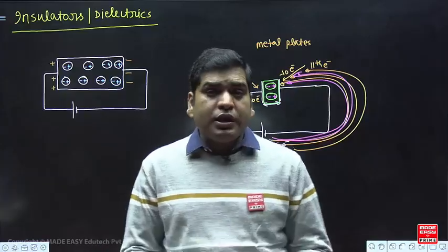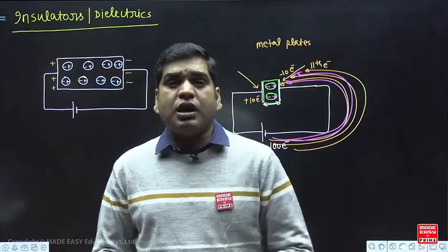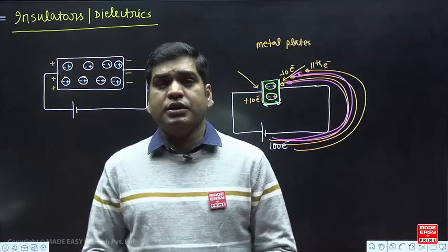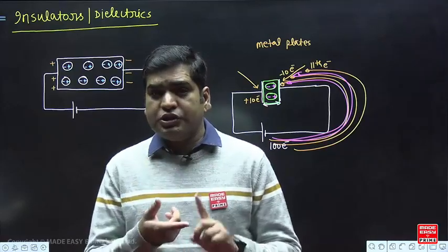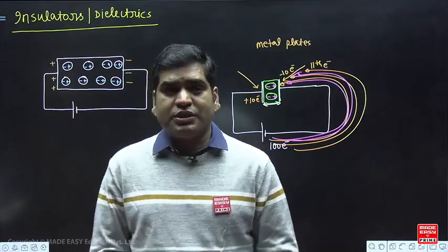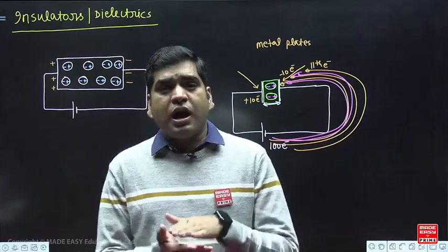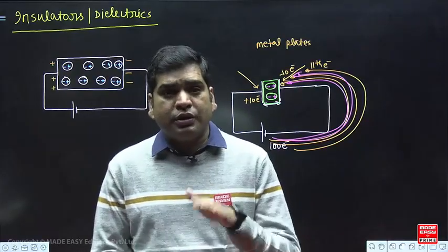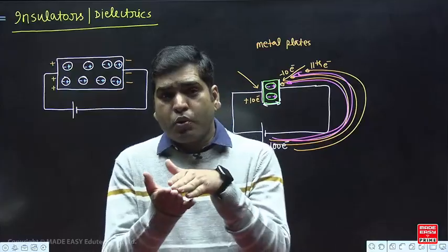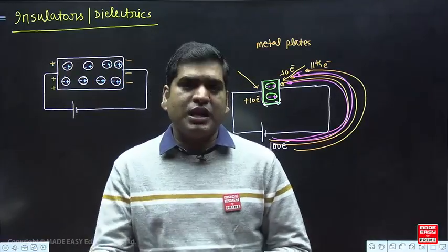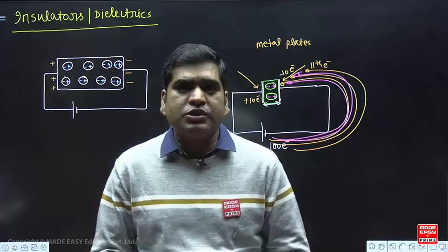Here we are bothering about the resistance of the plastic. If the resistance of plastic is very high, then it will isolate the user and the live conductor. So the user will not get a shock. So here the purpose of this non-conducting material is to provide electrical isolation between two conductors. One is the live conductor wire and another is the user.